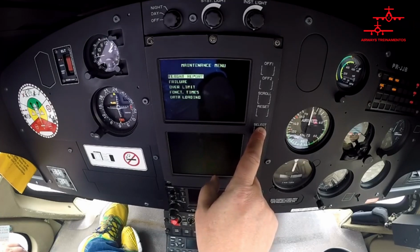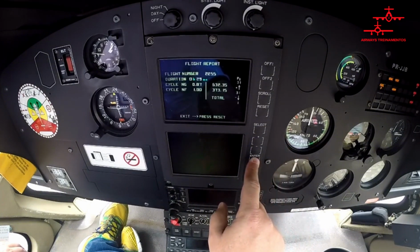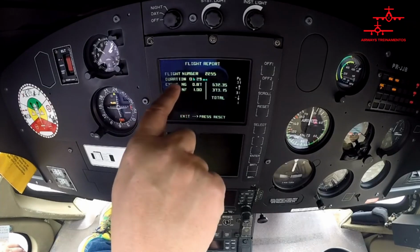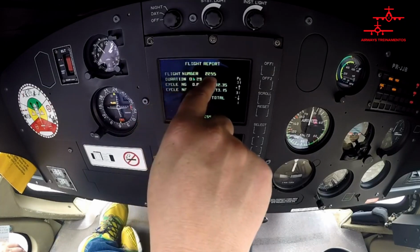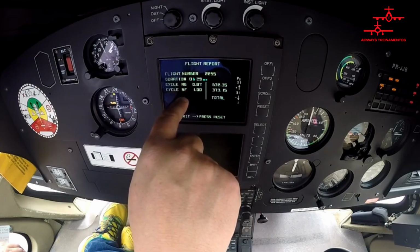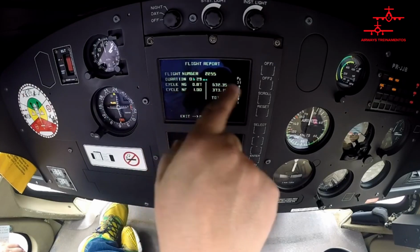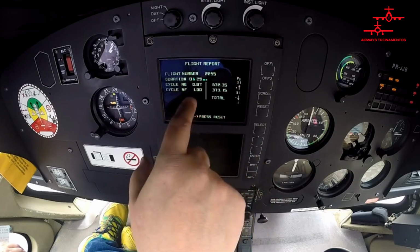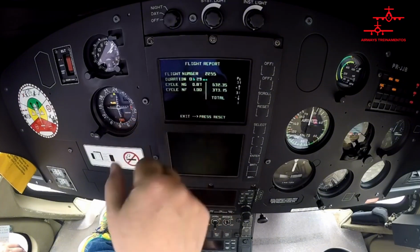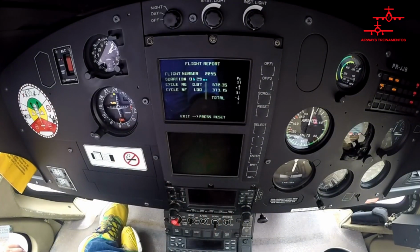So I'll select fly report as we normally do. And then I have the last flight there, right? How many cycles there were, the duration of the flight. It keeps accumulating the number of flights and gives me the cycles here for NG and NF and the total. This needs to be recorded in the engine logbook because the cycles, these NG and NF disks, are tracked by cycles. So the VMD does this calculation. The company's CTM staff keeps track, accumulating it in the control spreadsheets and recording it in the engine logbook.